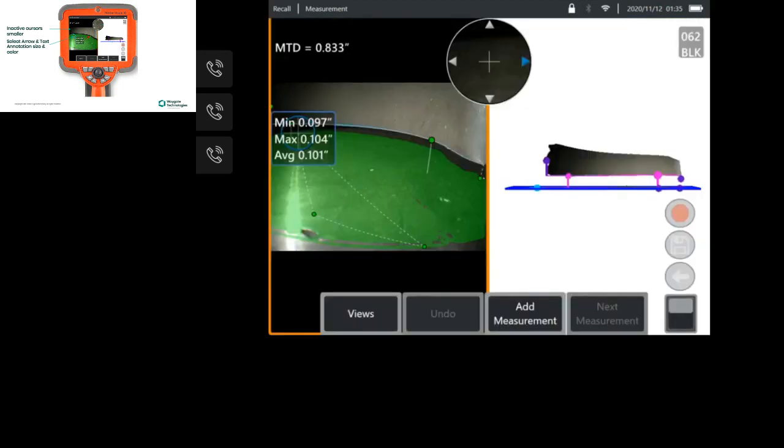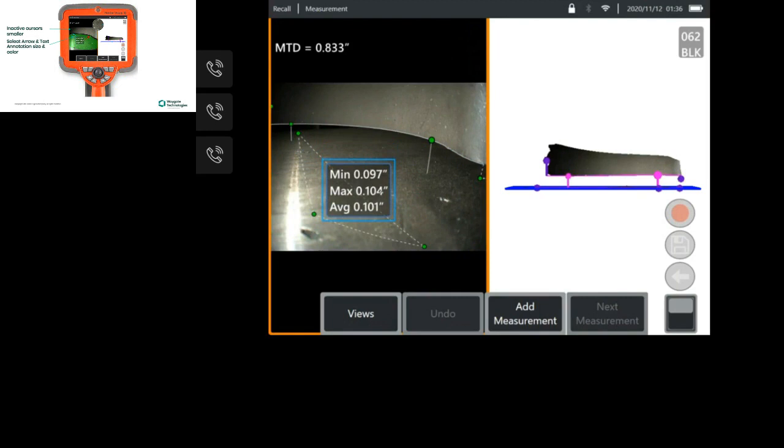I can select that, and it is automatically going to place the measurement plane. That is the 3 cursors that are on the shroud with the surface mask in green. That is cursor 1, cursor 2, and cursor 3. Now I have additional cursors. Let me move the measurement results out of the way so that I can declutter the screen.